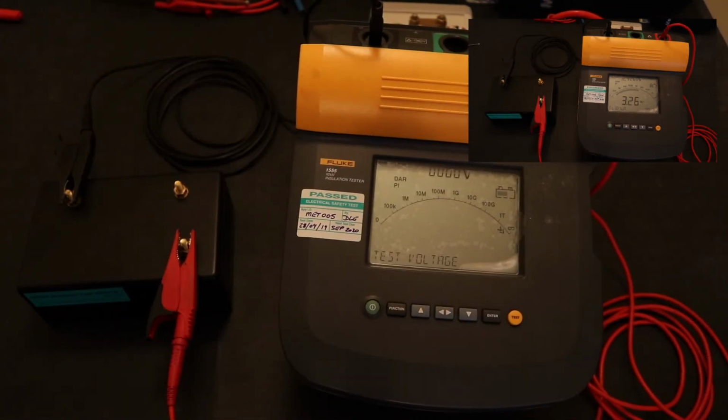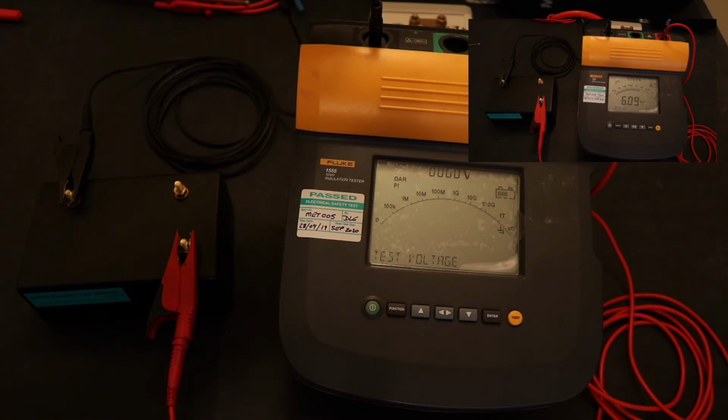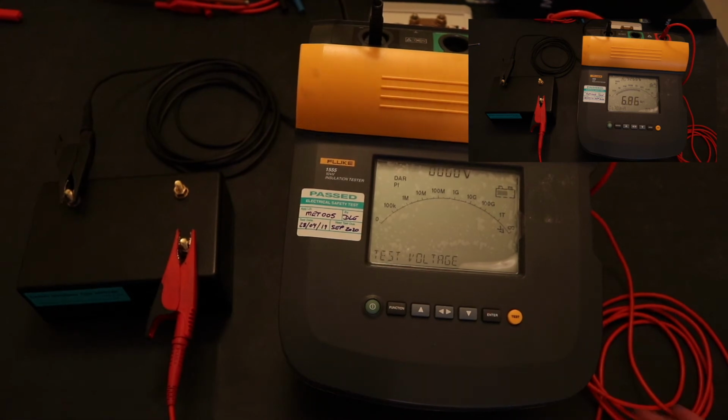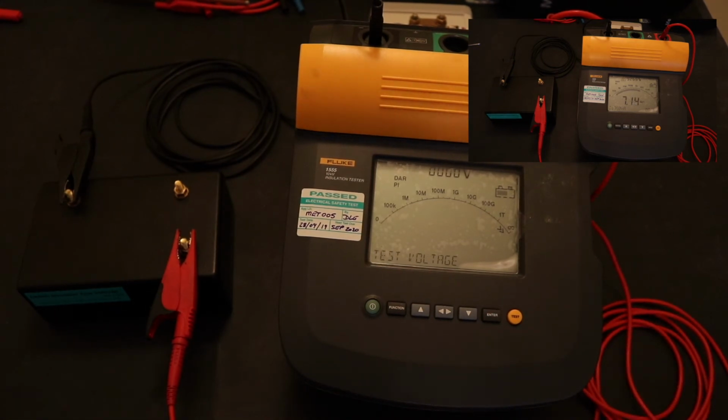So with the test set up, you can see I've actually, because I'm going to be testing at 5,000 volts, there is a danger that you can get leakage between the test leads at such a high voltage. This instrument from Fluke does have a guard terminal, but they don't supply shielded test leads with it. So I've deliberately configured the test so that the leads are well away from one another. You can see the black lead from the negative is coming around this way, and the red lead is over the other side, well and truly out the way of each other, so there shouldn't be any leakage between those two leads.